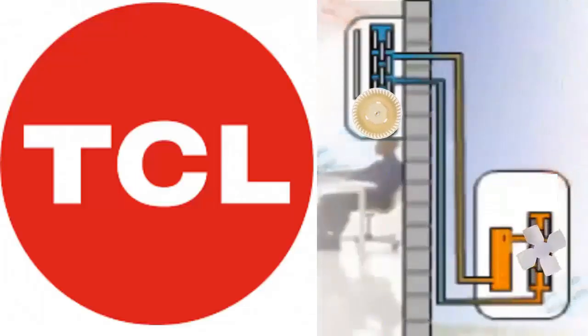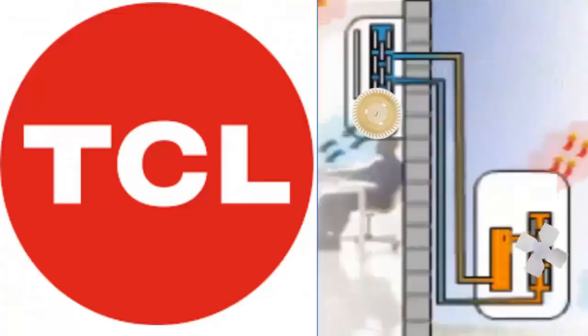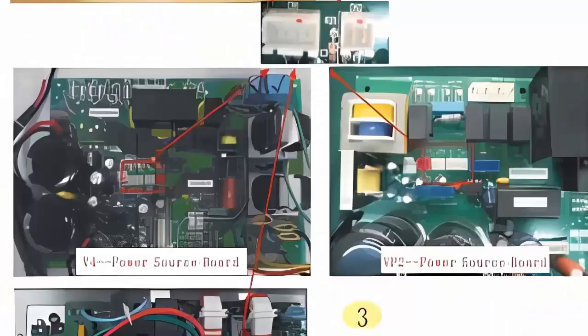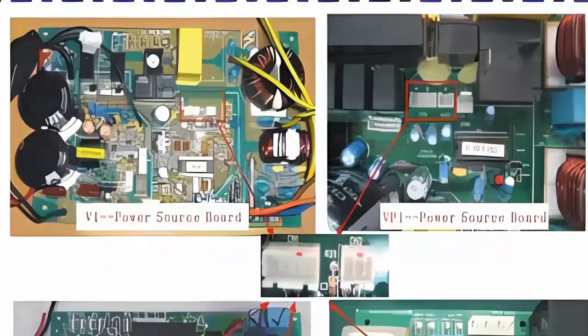8. If the error persists after replacing the sensor, it is very likely that the issue lies with the exterior unit's electronic board. In this case, a visual inspection of the electronic board for any abnormalities is recommended.